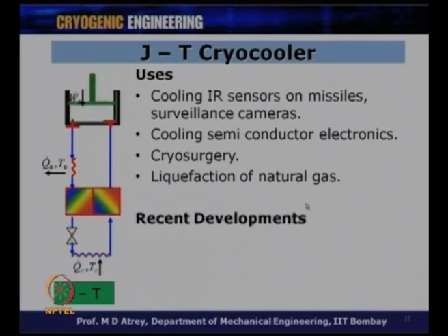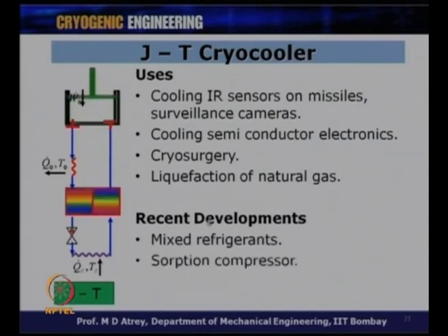The recent developments in JT cryocoolers are, instead of using a single gas, we can use mixed refrigerant. And if I use mixed refrigerant, my pressure limits are coming down. All right. So, this is a very recent phenomenon, very recent developments happening in this field.